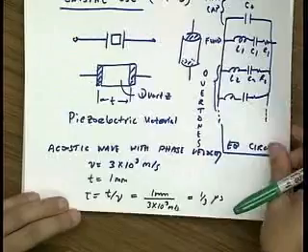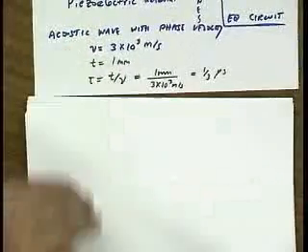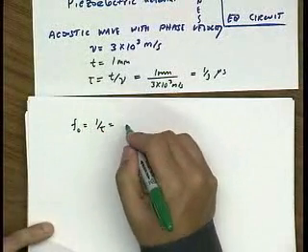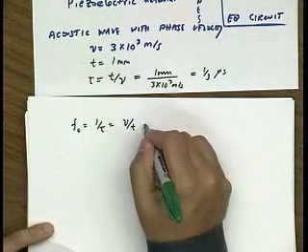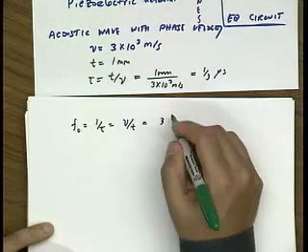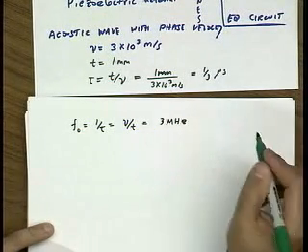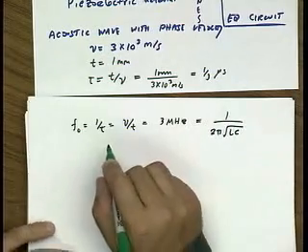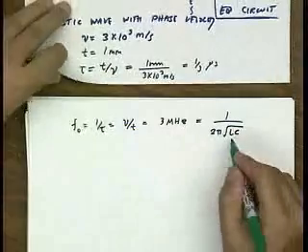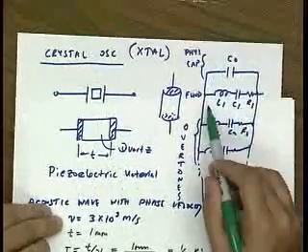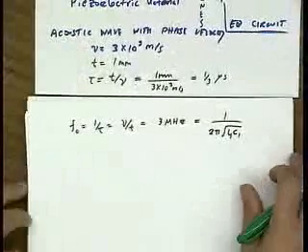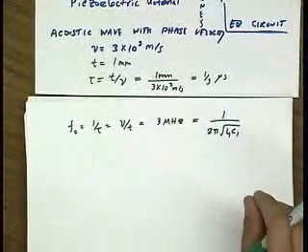Okay. And that corresponds to a resonant frequency, f0, 1 over tau, or just velocity over thickness, of 3 megahertz. Okay, and so our equivalent circuit here, the first mode, L1C1, should resonate at 3 megahertz. Okay, so we know how to pick the product of L1C1.